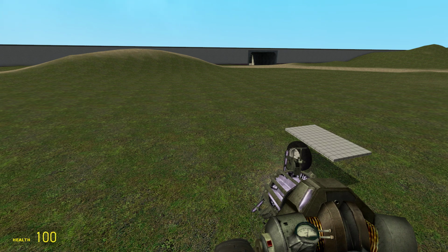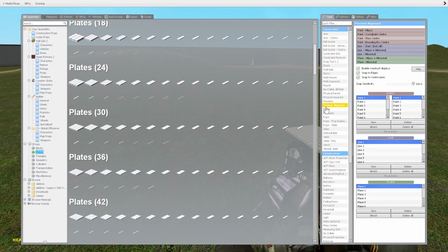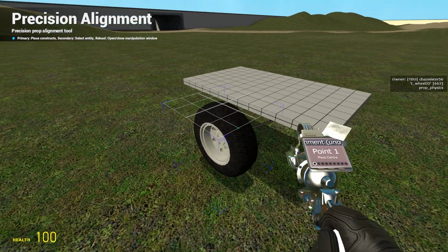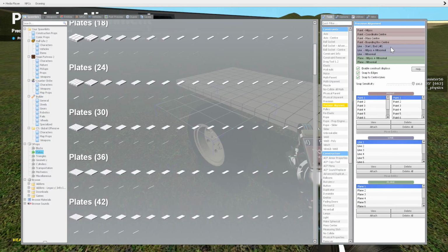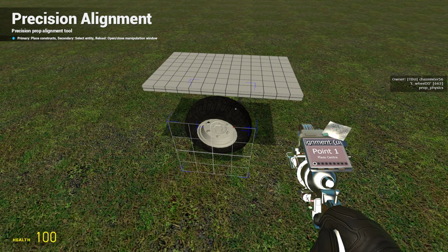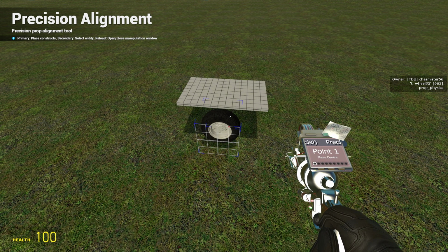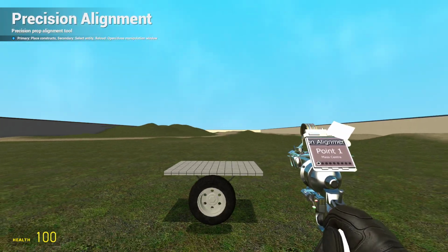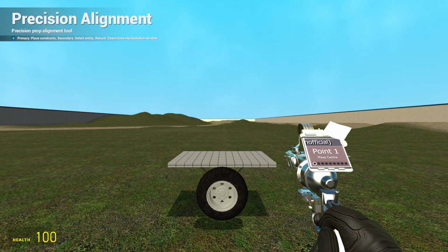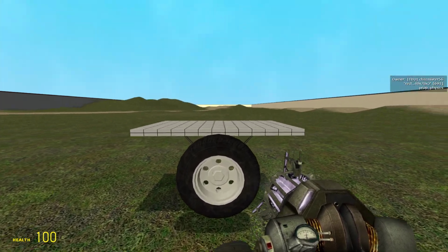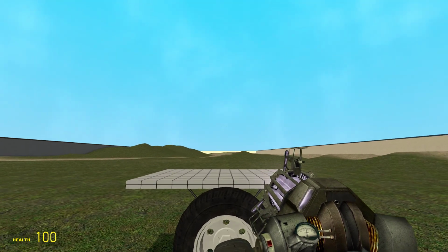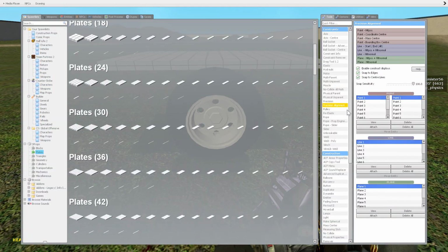You right-click the controller, and hydraulics are nice. And I mean, you can still do this method with hydraulics, but the better choice for your suspension is elastics. Now, this will work on both elastics and hydros, but on hydros, do not set the length setting when you do this, because it's going to be in the very center of the wheel. It does not need a length setting. When you actually have it above the wheel, you're going to need a length setting, so you can set the distance from the actual attachment point on the suspension to the wheel.